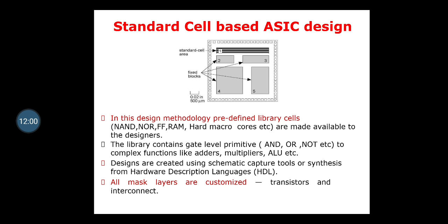The library contains gate level primitives like AND, OR, NOT, etc. to complex functions like adder, multiplier, ALU, etc. Designs are created using schematic capture tools or synthesis from hardware description language. Here the hardware description language is used. All mask layers are customized, transistors and interconnect.